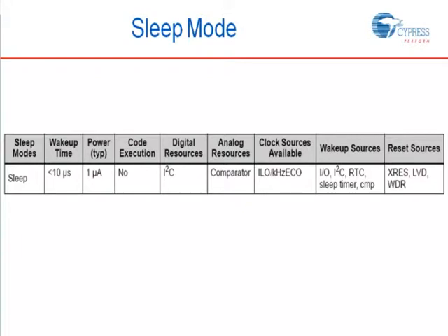Supervisory services such as the real-time clock (RTC), the watchdog timer, the periodic low voltage detection, and the sleep timer remain available in this mode. The fixed function I2C block and the comparator block also remain available in this mode. The internal local oscillator and the external 32 kHz crystal, if connected, will be active during sleep mode.